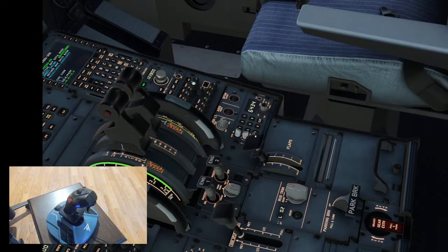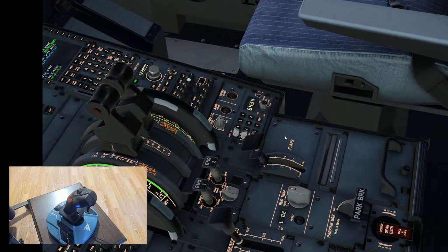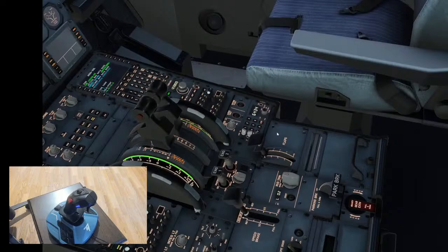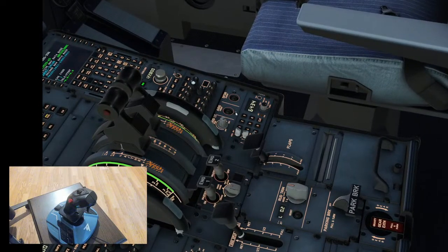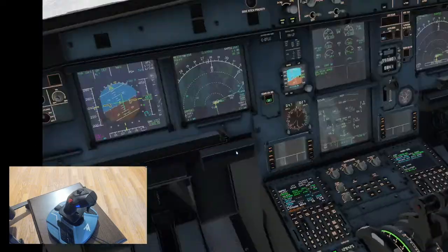I mean, during flight, if any dangerous approach, both aircraft or more than both aircraft approach or collide with each other, the system first warns as traffic, something like this. And then if the pilot does nothing, it will give a warning: descend for one aircraft, and the other aircraft will increase your climb, something like this, an avoidance system.